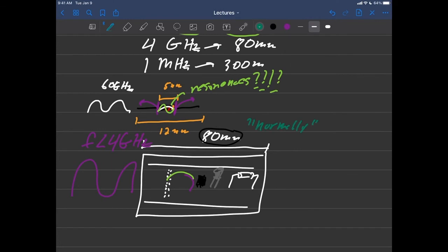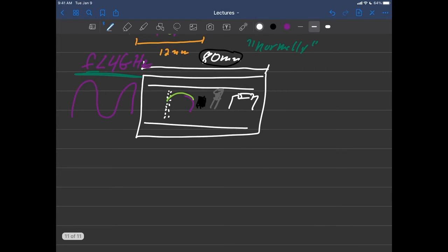And I don't even know what that means, but if you wanted your circuit to behave the way you're anticipating it, you might want to avoid frequencies like that. Now, you probably never had to think about this before, because commonly in undergraduate electronics, we do a lot of DC electronics, of course, and that's just a frequency of 0. So you're nowhere near any resonance or anything like that.